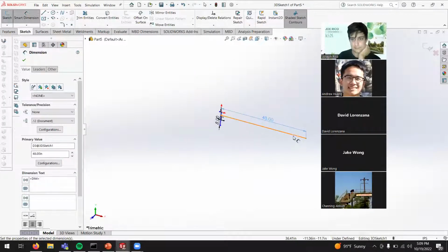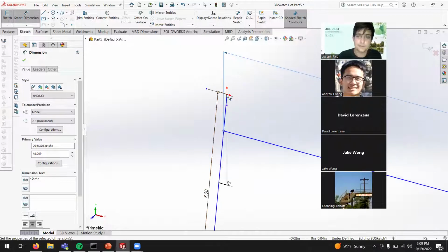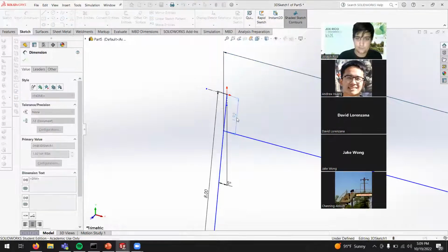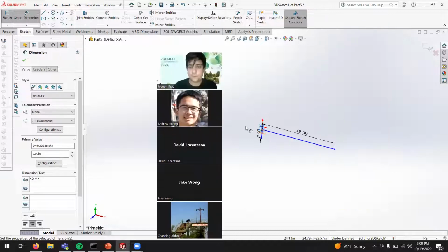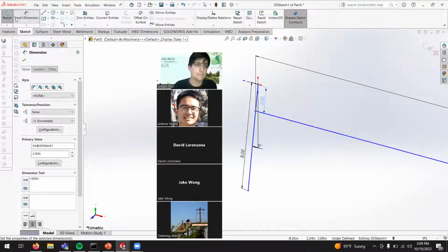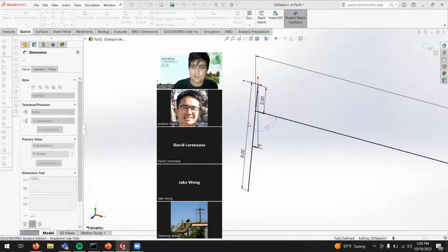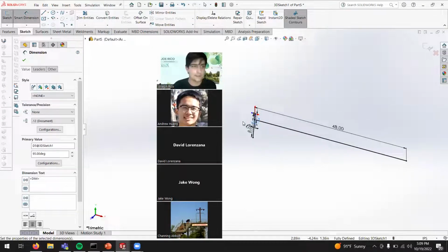That looks a little, that's fine. Yeah, big bike. Okay, and then you could say, depending on how much we carry, about 2 inches. Next up, I want to make sure that we know that we're all perpendicular, and this is all pretty much just regular sketching stuff. 95 degrees, and that makes sense because it's sitting parallel to our x-axis, and our head tube is off by 5 degrees, so you expect to see 95 degrees there.